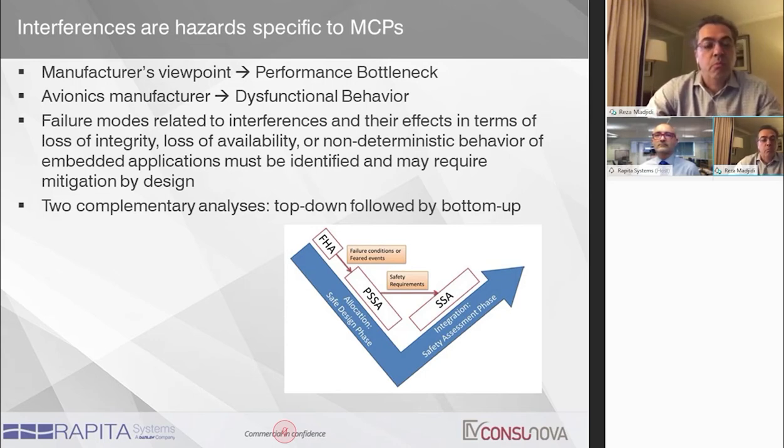If you go back to single core or typical avionics, the safety concept starting from the FHA, PSSA, SSA, and the fault tree analysis is still valid and needs to be done, top-down and bottom-up, and it applies to MCPs or multi-cores. It is more difficult, especially when you move to design assurance level A, DAL A.